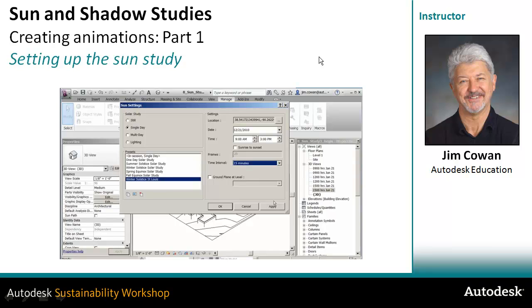In addition to being able to create settings for a particular time of day, you can save settings for a range of times. So under the Solar Study single day, you can give a beginning time and an end time, and you can specify the interval. So in this case, at 15-minute intervals, you'll be seeing the shadows as they affect the site. Now this means that you can apply those settings to an individual view.